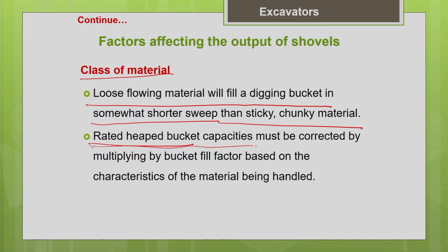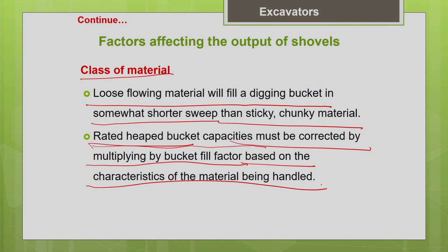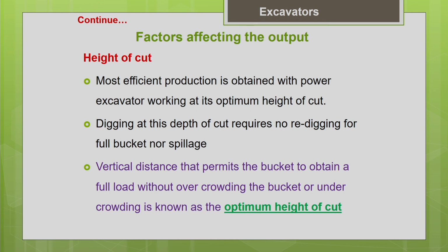Rated heaped bucket capacity must be corrected by multiplying by the bucket fill factor based on the characteristics of the material being handled at the project site. Now, another important factor which we are going to discuss is the height of cut. Let us see how this factor is going to affect the productivity.